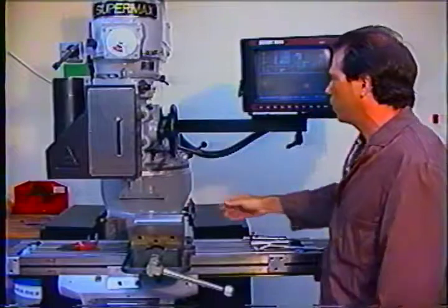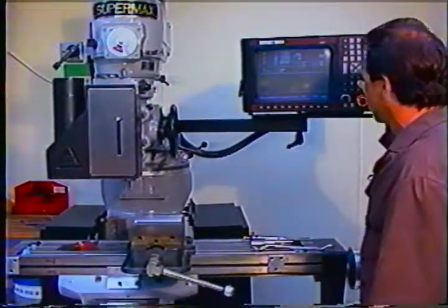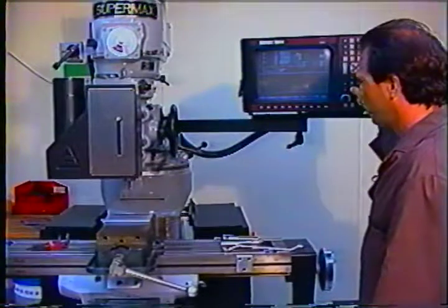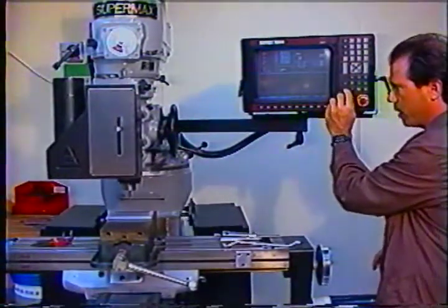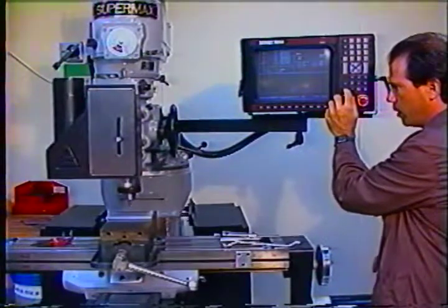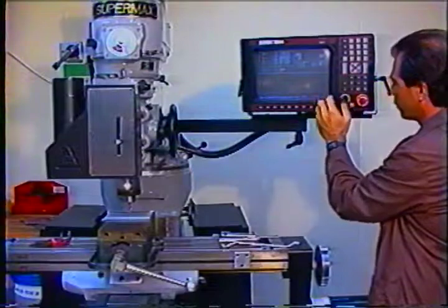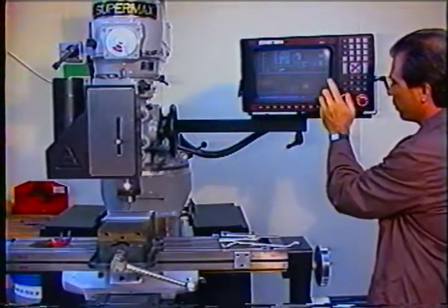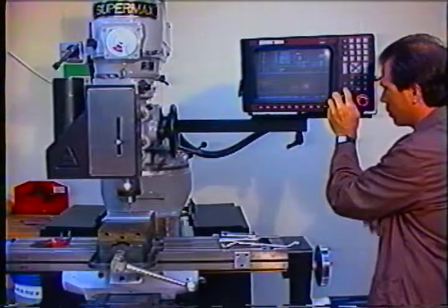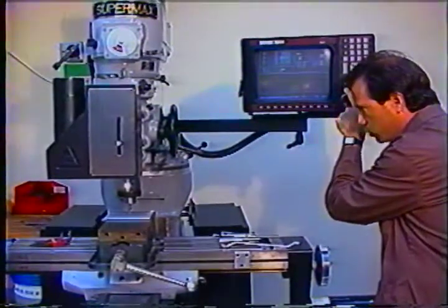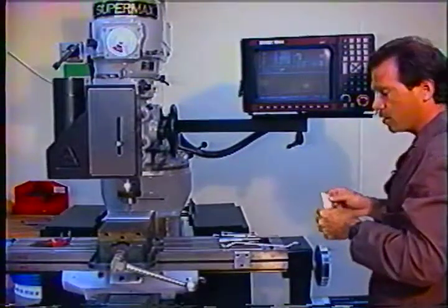Tool number 1 is in the spindle. I'll set my jog status to rapid and rapid over the top of the workpiece. I'll override my feed and I'll rapid down slowly near the center of the part. And I'll switch to feed jog, bring it down all the way to 10%, and slowly creep Z-axis down till I'm close. Okay, one method of doing tool offsets is to use a piece of paper,